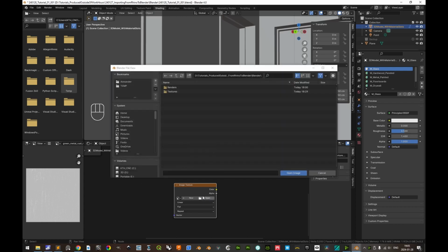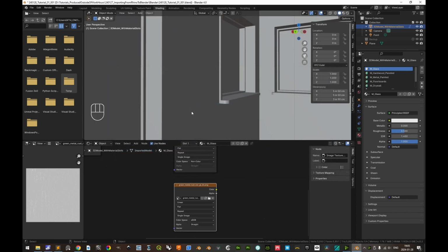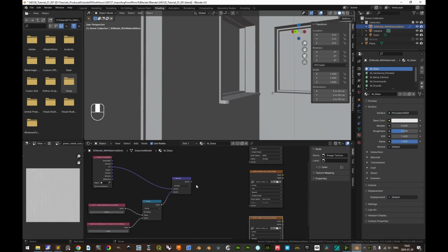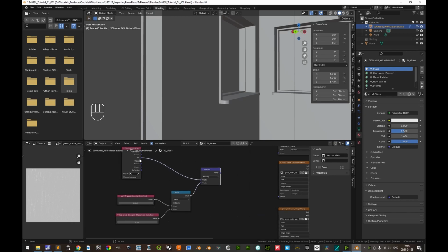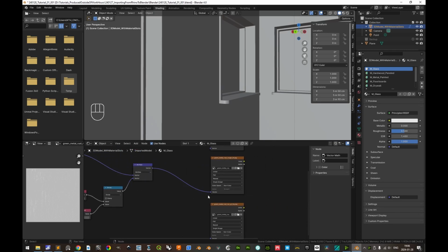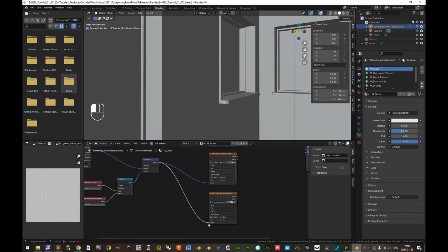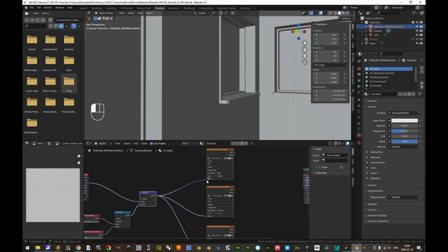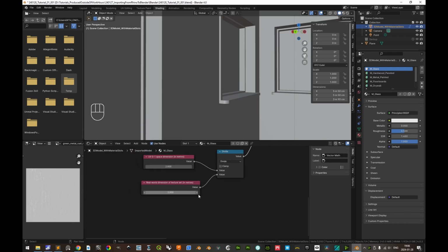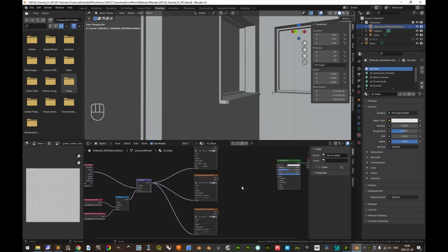All right, and then for the third and last one, we'll open, and then we can just paste that directory there, and then we can open this one, the normal one, and then this one also non-color for color space. Very good. And then this vector that we get from multiplying the UV coordinates with the ratio between the UV 0 to 1 space and the real world dimension, we make sure to have as our input vector. This makes sure that the textures can be scaled with this value node here. All 3 textures can be scaled uniformly.